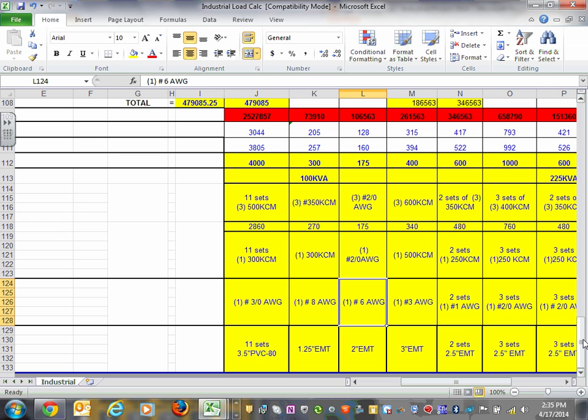When I teach wiring, Mike, agree or disagree with me, I always say if you're indoor, your conduit of choice is EMT. If you're underground, your conduit of choice is PVC. Now there are other options, right? For the most part, if you have physical protection or a hazardous location, rigid threaded. Between EMT and PVC, guys, it solves 80% of your wiring methods.